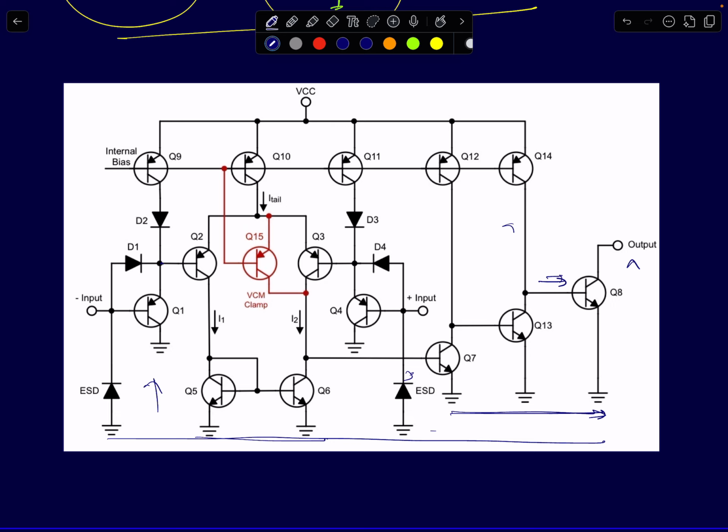So kickback noise, to summarize, can lead to false triggering. Your comparator's output will not be stable, even if your input goes lower than the reference signal, the threshold voltage, for some time. To avoid that problem, we have to decrease the kickback voltage at the differential input pair. And to decrease that, we just added a common collector configuration. Common collector configurations are famously known for their very low output impedances.